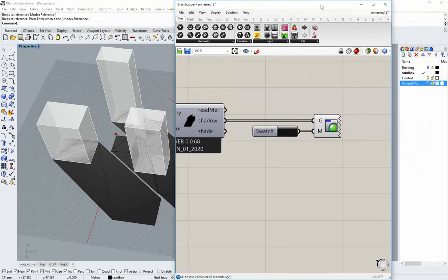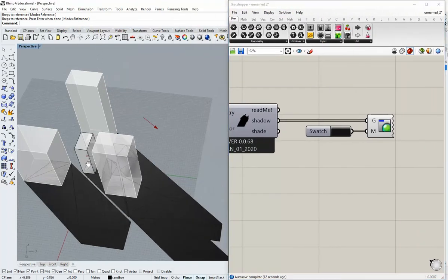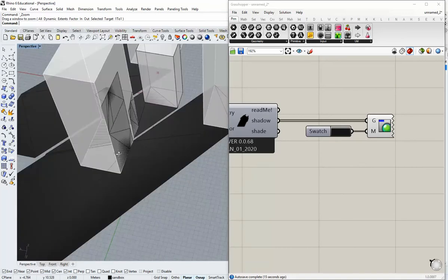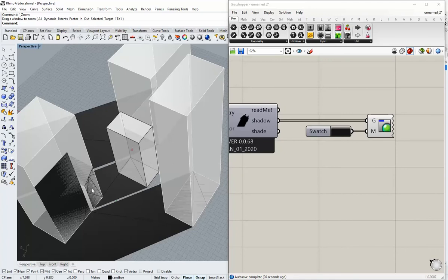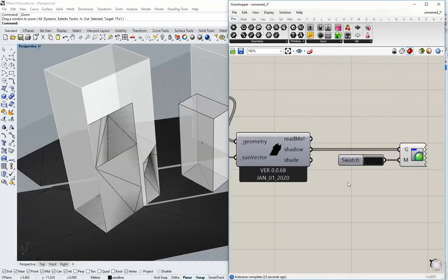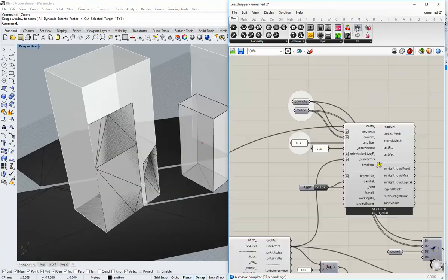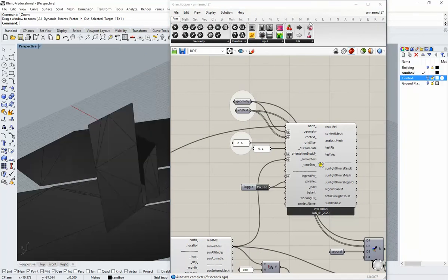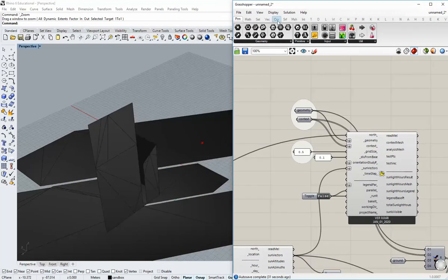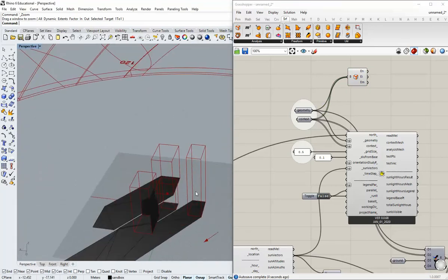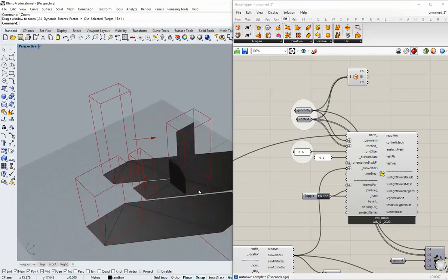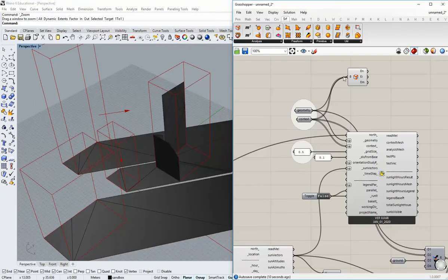And what I'm going to do is turn on the building here. There we go. Let's zoom around, play around a little. It's pretty nice. Another thing I like to do for this one, we're getting this overlapping preview going on here, so it's not a bad idea to turn these layers off in Rhino. And then we'll go to surface, grab this B-rep edges component, and take a look at our B-reps just as edges, almost like a wireframe, which is kind of nice. You can change the color of that if you like.